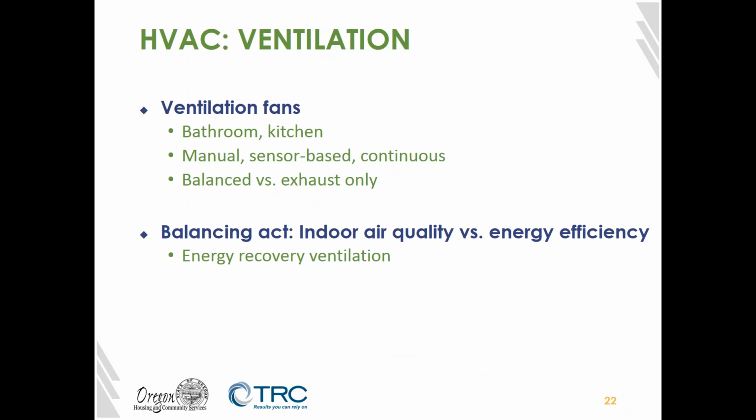So I've been talking about the heating and the air conditioning, the H and the AC of HVAC. For the ventilation, you'll see a variety of things. A lot of units will have some form of ventilation fans, bathroom or kitchen fans. Not all of them necessarily, though. But the bathroom fans in particular can be upgraded, and it is incentivized to a fan that has a sensor in it, either based on a humidistat or a motion sensor, or both. And kitchen fans, sometimes you'll run into fans that are hooked into the stove, where they only turn on when the stove is on, but that's less common.